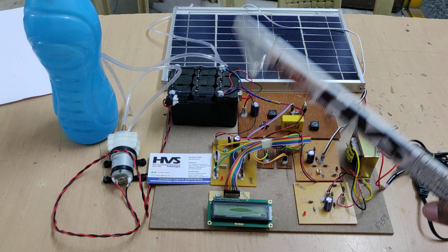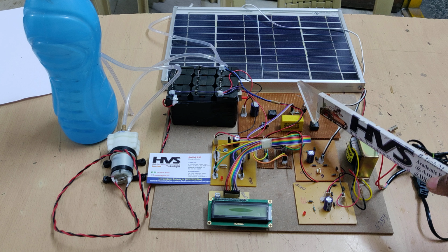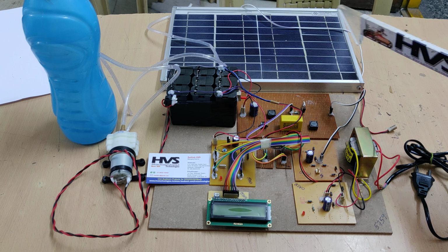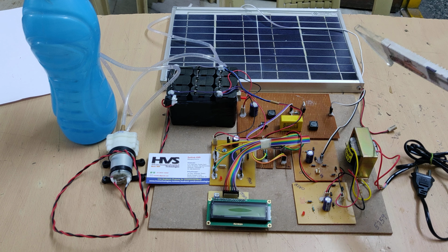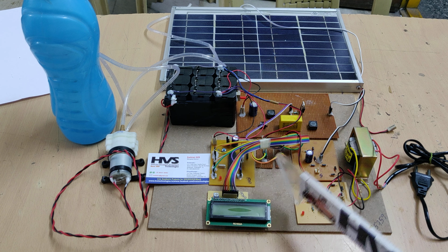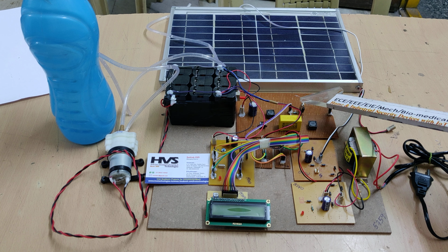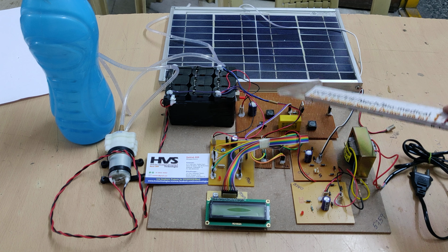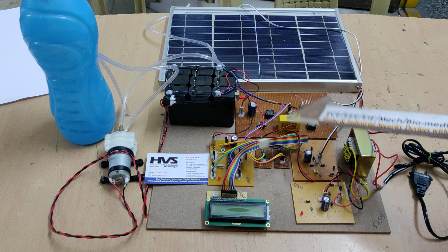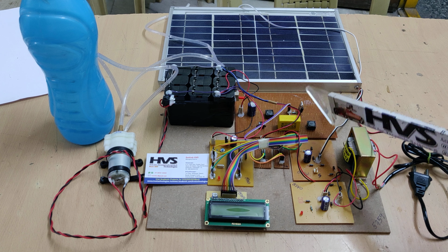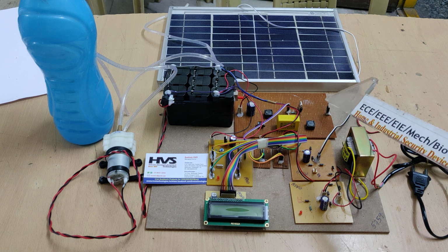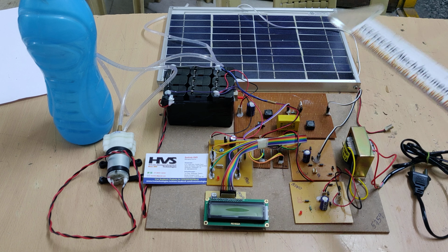Then our system will control the voltage with the help of this SEPIC converter in order to gain the maximum power. Whenever the voltage crosses 14.5 volts, as it reaches toward 18 volts, our microcontroller will start controlling the trigger pulse, meaning the duty cycle to this MOSFET, to reduce the output voltage of our SEPIC converter. Then the voltage will be regulated and locked at 14.5 volts, and the current in parallel will be increased.